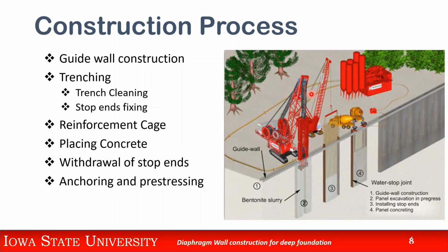Then I have the excavation tool or instrument, which lowers in the guide wall and excavates a panel. You do not excavate all the wall in one go. You excavate it panel by panel. So you excavate the first panel, which is like the trenching process. When you excavate one panel, based on the groundwater level, water might seep in from the sides,